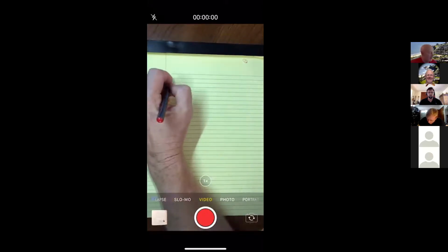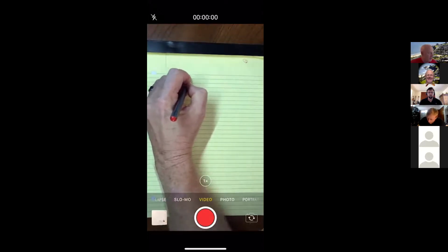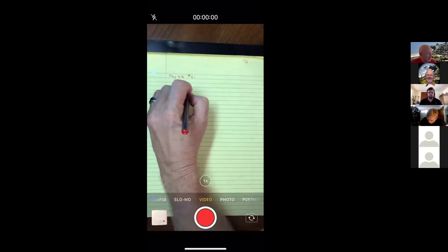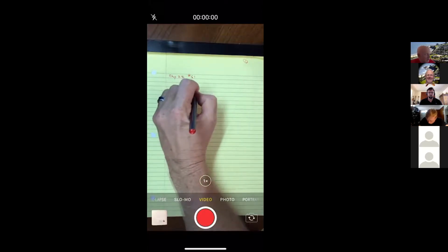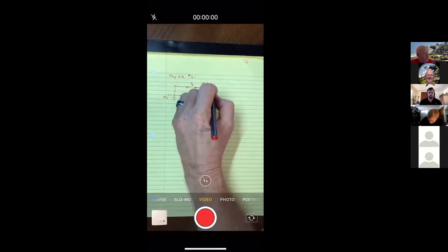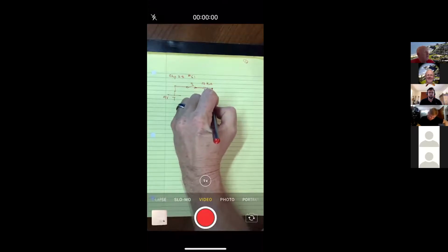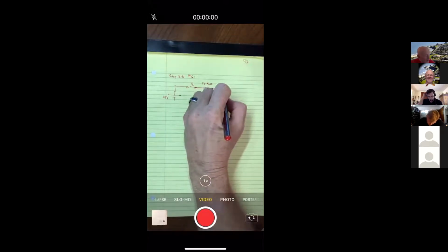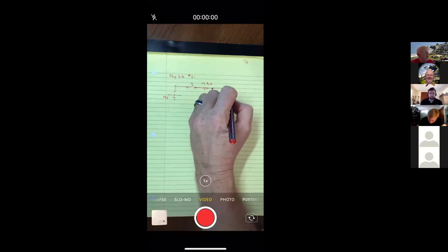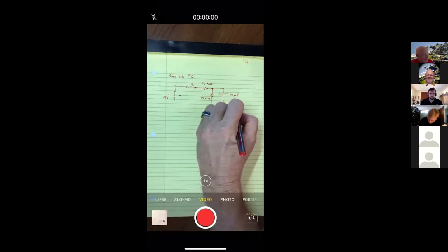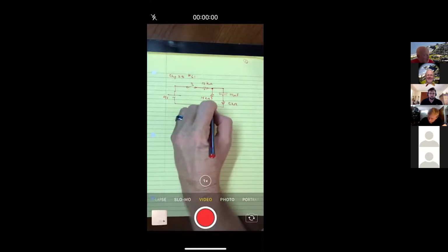So 61 looks like this. So chapter 28, number 61. It looks like it has a battery of 9 volts and then a switch that then runs through a 12 kilo ohm resistor. At that point, it hits a node and it splits. If it goes straight down to resistor 2, they call it, it's a 15 kilo ohm. On the other hand, if it continues in this loop, there is a capacitor of 10 microfarads and another resistor of 5 kilo ohms. So there's some kind of RC time constant going on here.